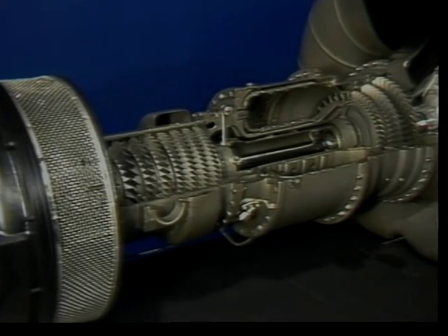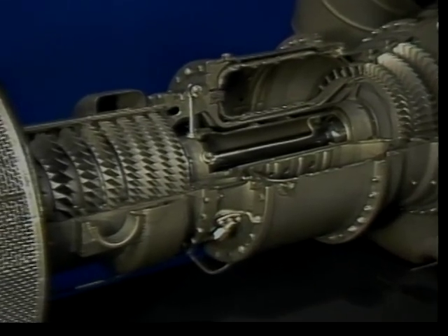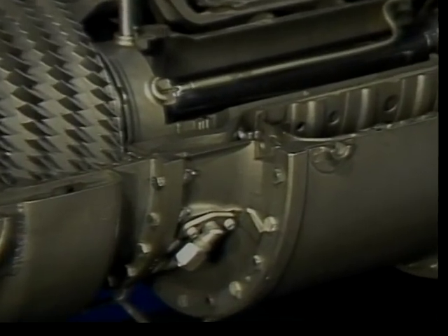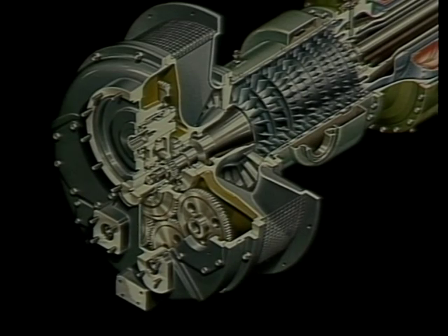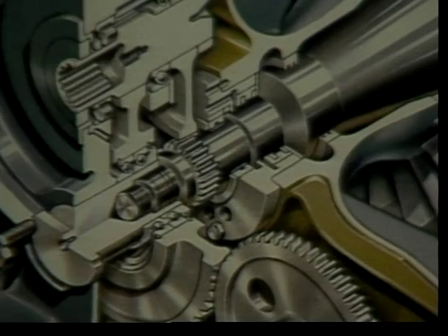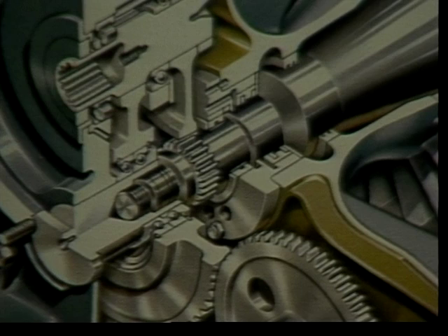The gas turbine engine consists of several basic subassemblies which are connected in line using attaching bolts at the housing or case flanges of each subassembly. Starting at the forward end of the engine, the accessory drive assembly provides input and output drives of required rotational speed through a series of gears. A pinion gear is located on the forward end of the shaft to drive the accessory drive gear train in the air inlet assembly. Mounting pads are incorporated on the accessory drive housing for the main lube and hydraulic oil pump, speed governor, starter assembly, and liquid fuel pump when used.